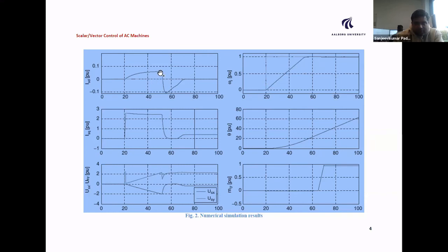Obviously, then during the steady state period, so this is an oscillation period. And this is the speed response. So initially it is 0 until 20, then it starts to increase as the reference goes to the maximum value 1, tracks the value and reaches the maximum speed of 1500 RPM or whatever the machine parameter is. Here it's shown in per unit value.